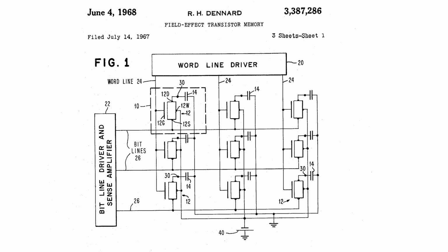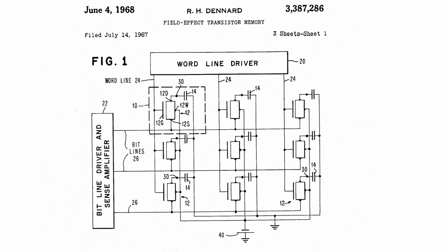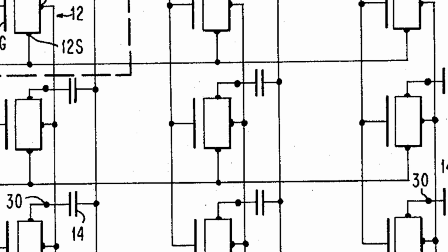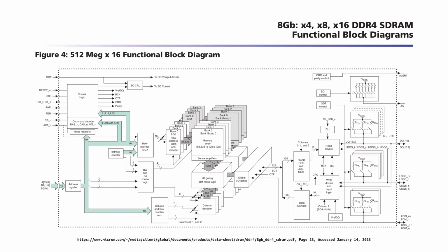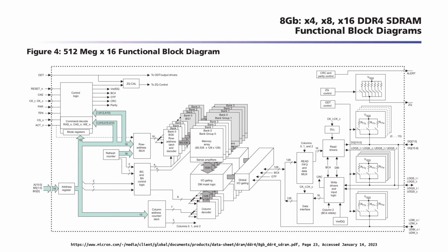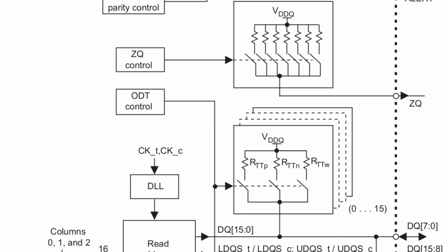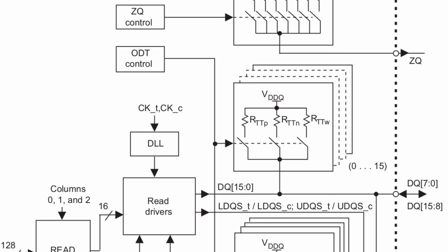In modern DRAM sticks, bits of information are stored in tiny capacitors. As you might expect, when you have a tiny charge stored in a tiny capacitor, it's easy for the charge state to get corrupted, which corresponds to a bit flip. When information is finally read out from memory, the charges in these tiny capacitors must be amplified by one of the aforementioned logic families. This amplification is yet another potential source of error.